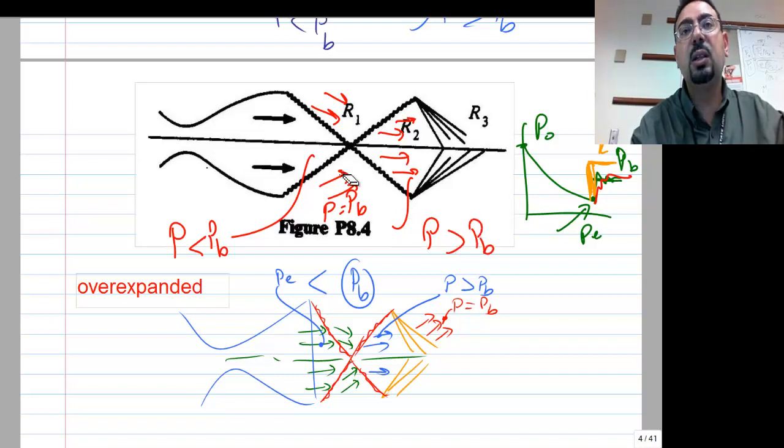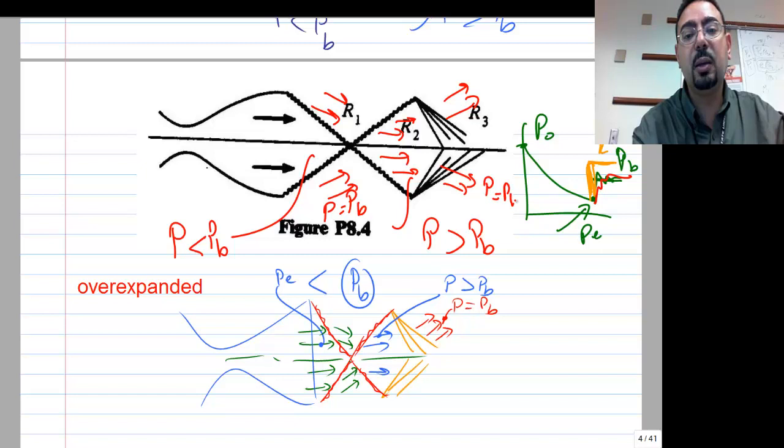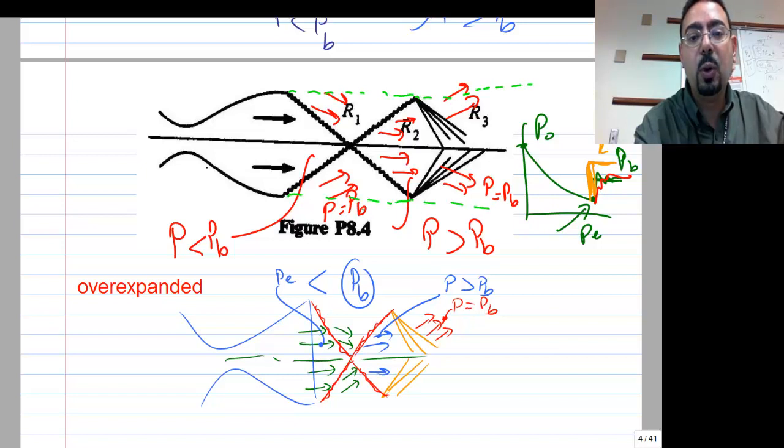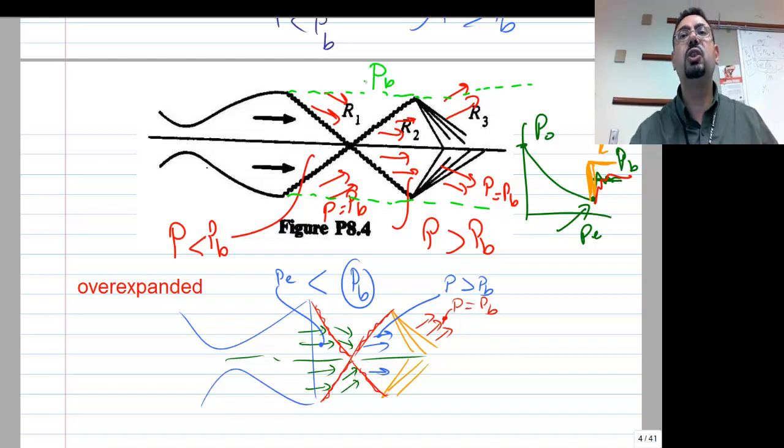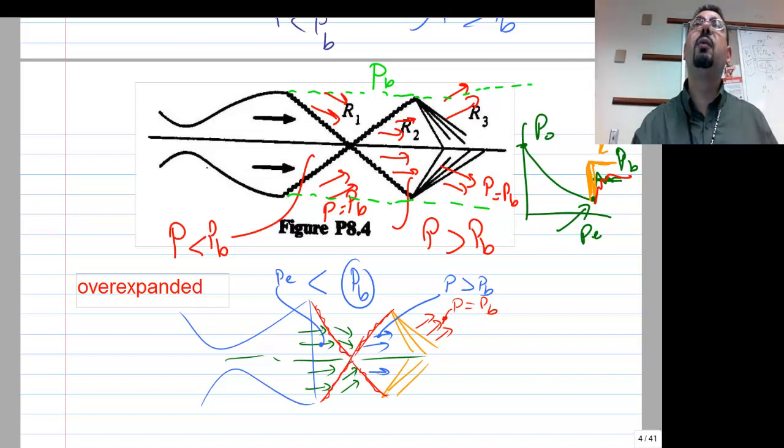So once the flow touches the exit, the free boundary, it basically expands with an expansion fan that will take it outward, but it adjusts its pressure. So here the pressure is P back. And that free boundary or pressure boundary I'm referring to is where the flow touches the ambient and gets adjusted to it. But the point is, this basically keeps going forever.